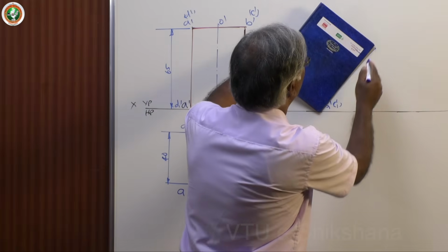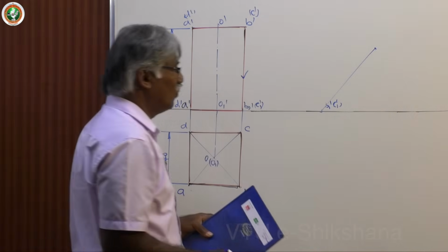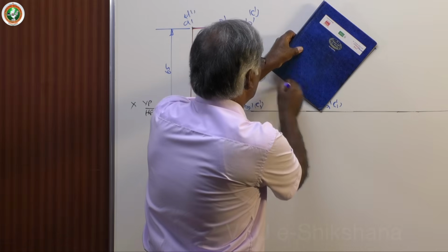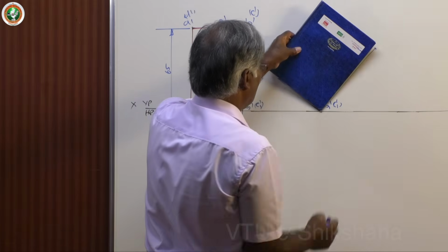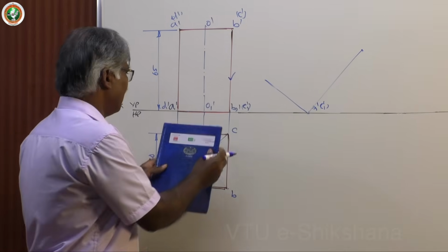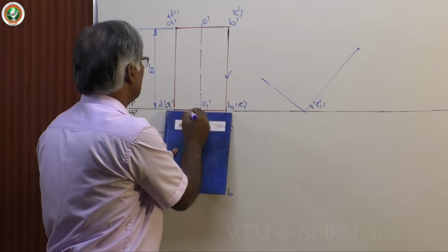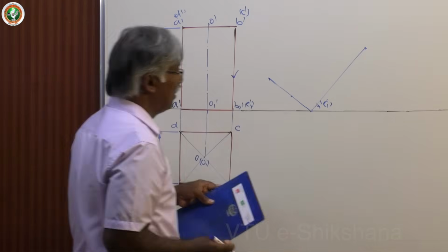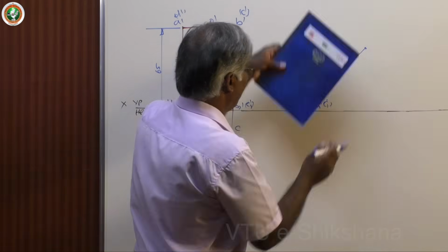Now draw perpendicular using a protractor. Manually, if you are doing it on a sketchbook, and on a computer it is easy, move and rotate. Then take all these distances with a compass and do it. Then draw perpendiculars.